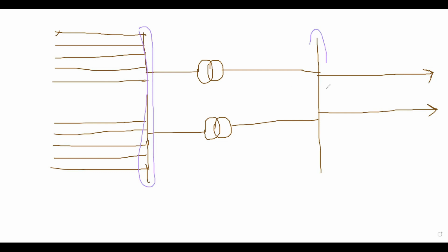What is the chance of failure of the bus at 220 kV level and at 33 kV level? And is this configuration the best, or should any other configurations be adopted? Again, the concept of reliability. The reliability analysis will give you what type of busbar scheme to be adopted in your system. We have different busbar schemes, team.